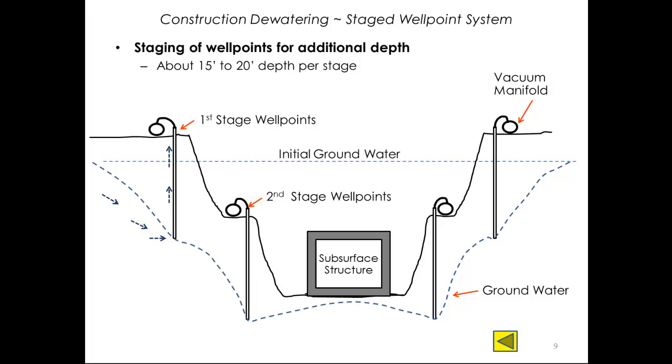But that's not a major problem, because if we have to excavate deeper, we can stage the well points as you see here every 10, 15, or 20 feet, and it's possible to stage these 5, 6 times, and I've seen well point excavations deeper than 50 feet.